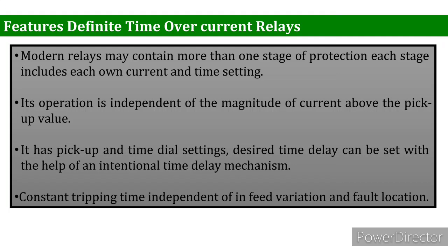Next, it has pickup and time dial settings. The desired time delay can be set with the help of an intentional time delay mechanism. This is the feature that I discussed in the last slide. You can also say the constant tripping time is independent of infeed variation and fault location.